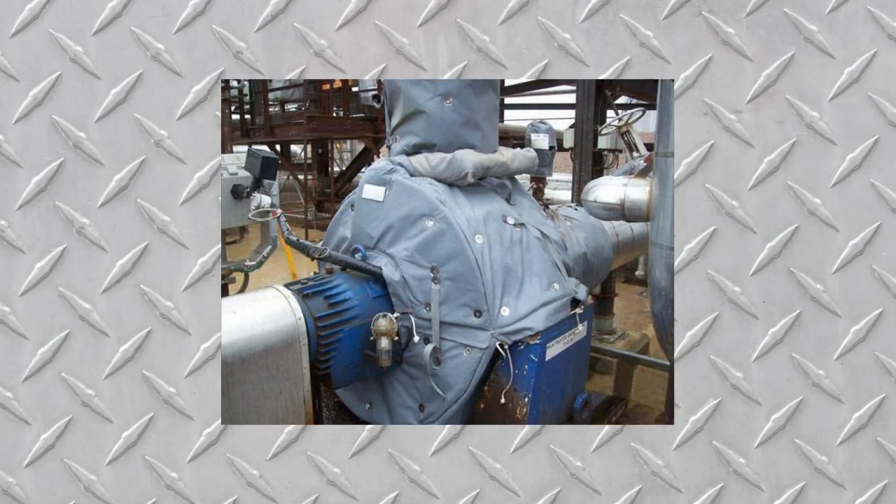Also, one of the things that should be obvious, but is not, is cleaning. We often see motors that get coated with dirt and are not cleaned regularly. That dirt can act as an insulator and cause the motor to run hotter. A hotter running motor is going to degrade lubricants and cause trouble in the motor core and increase the I²R losses. Dirt is not the only kind of insulation we see. In some cases, you'll find sound insulation surrounding the motor because they make noise. However, we find that in most plants, unless it's a very quiet plant, sound insulation is unnecessary and raises the temperature of the motor significantly.